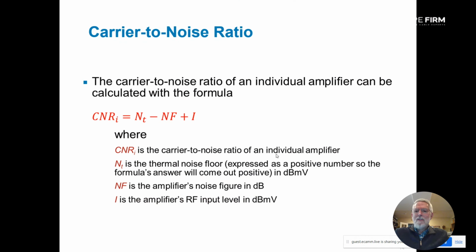And of course, that takes us to how to calculate the carrier to noise ratio of just, say, an amplifier sitting on the bench by itself. And this would be a line extender, trunk amp, or whatever. If you want to calculate the carrier to noise ratio of this amplifier by itself, now you're sitting here thinking, why is Ron talking about all this stuff? Isn't this something the vendors do? And the answer is yes, they do, but it's good to understand how they come up with a carrier to noise ratio spec for their equipment, because they'll calculate it first and then they'll measure it,